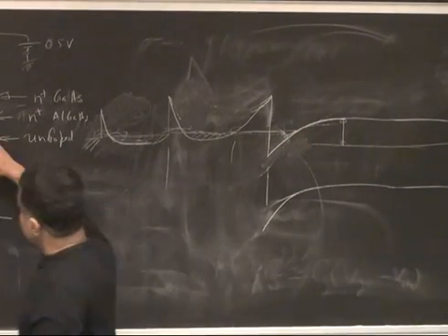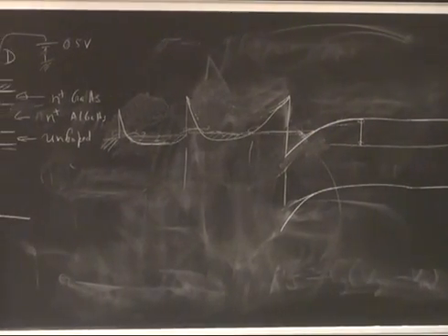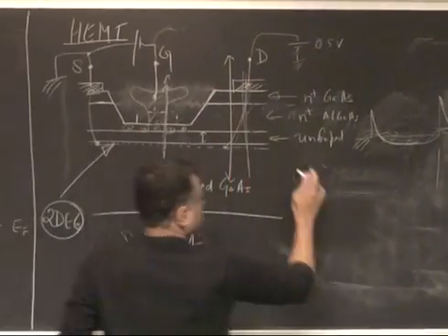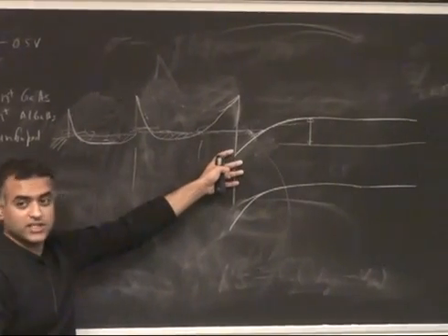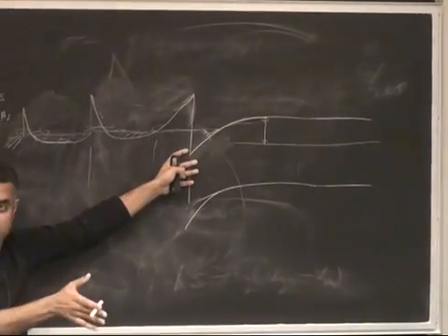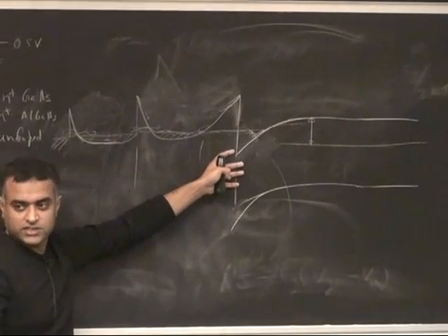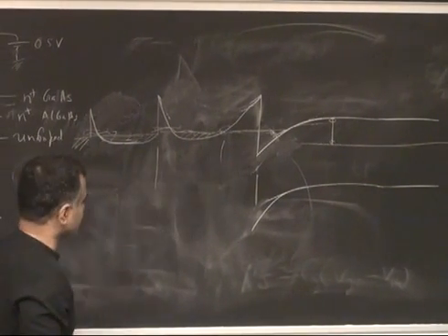For even higher performance, people don't use this structure. So you see, this is the ohmic contact. Here, you don't want to modulate this electron gas. You don't want to capacitively couple to it. You want to couple to it conductively, with direct conduction. So it's designed for that purpose.